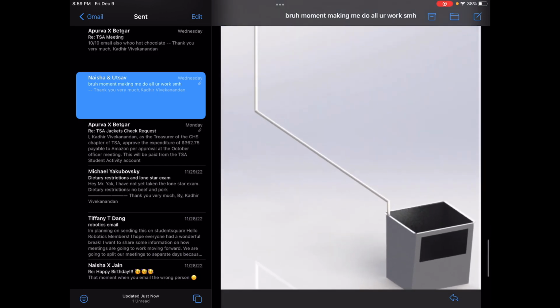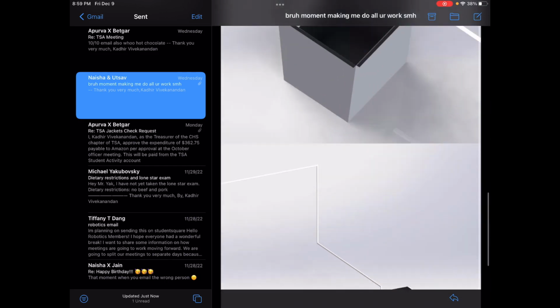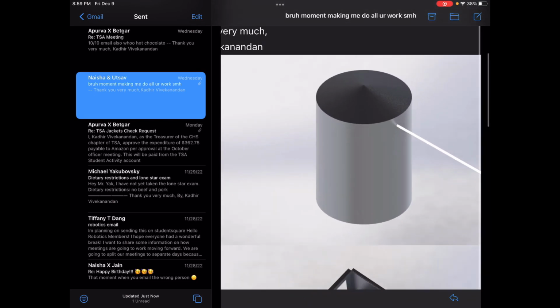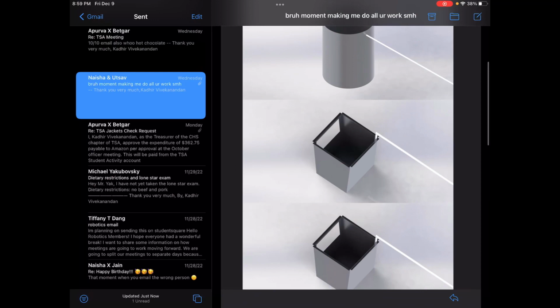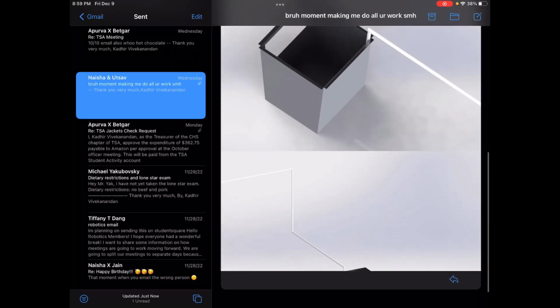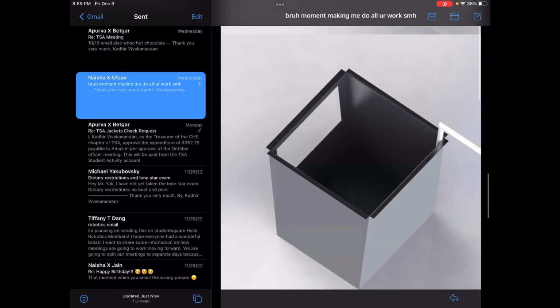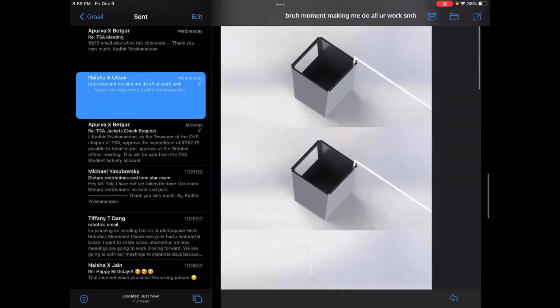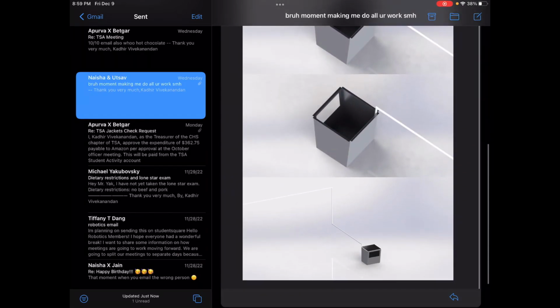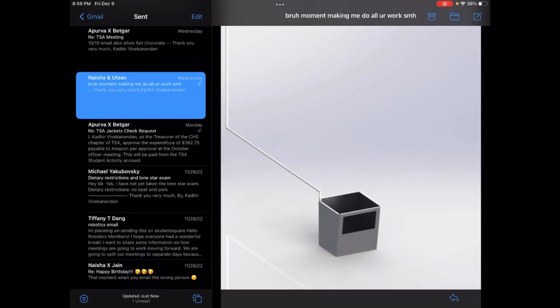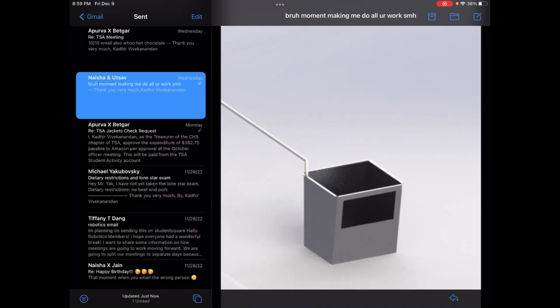As you can see, there's a PVC pipe leading out going into the cistern. Again, this is a rough model of the cistern, and the water will just fall back into the cistern from this. The water is going to fall into this collection unit, which is made of sheet metal, and will go into the cistern for storage. It's important to note that there will also be a filter located above this in order to filter out any unwanted particles, and the pump will be inside.